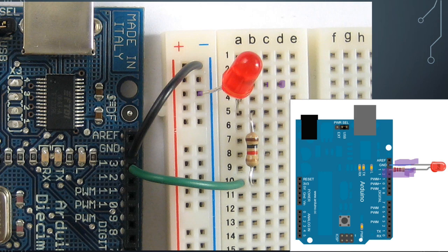And then we could put a wire running from this ground line over to row 3, and it would be connected. It just helps the LED, you're not pulling the wires apart so much, and it can look a little bit neater if you have several components to connect. So really, as long as you're making the appropriate connections and you're following the rules of a breadboard, you should be fine.